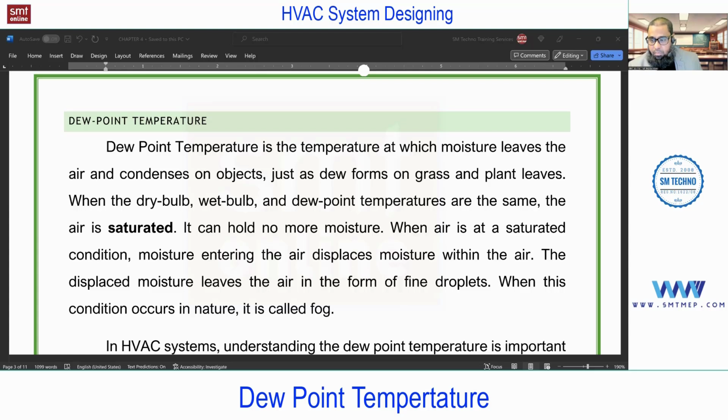I mean it will be very dry. Then how to maintain this 30 to 60%? You see, the first point is the evaporative coil is not designed to extract the complete moisture. Second point, continuously we are providing the fresh air.